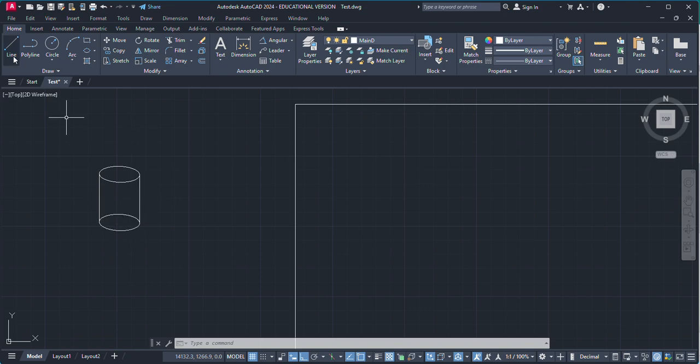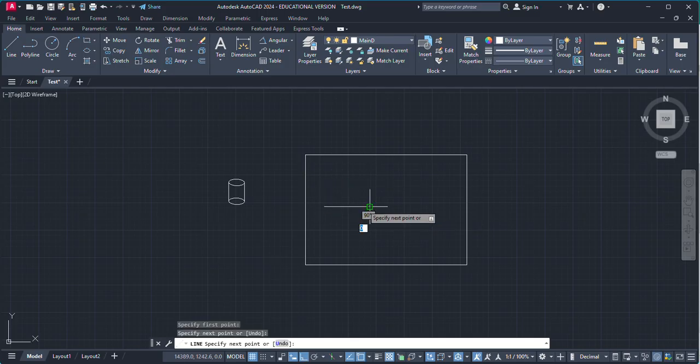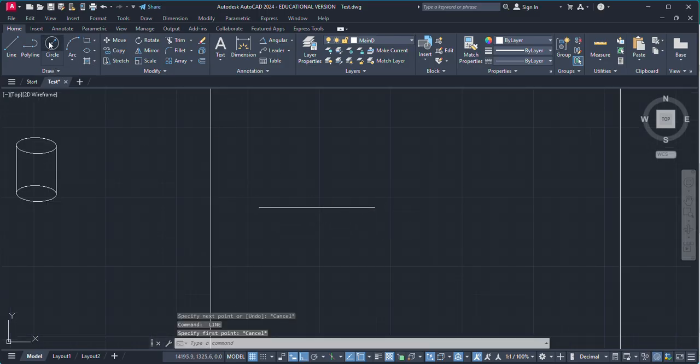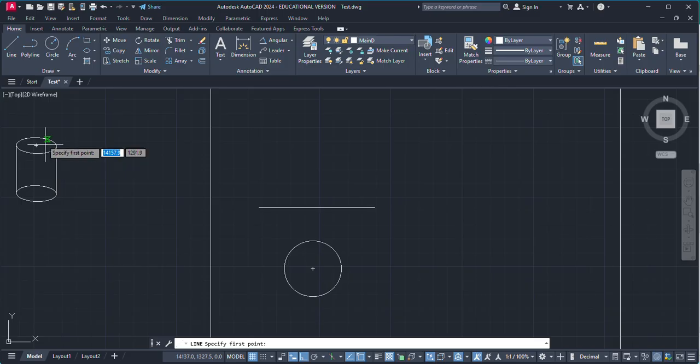view. So here this is the reference line, and suppose this is 40 mm diameter, so we will draw a top view of 40 mm. Sorry, instead of 40, we will take 20 radius. So this diameter is 40 mm. Now this is our top view, because in the top view we will have the circle, and both top and bottom circles are of the same dimension. So this is our top view, and out of this top view we will draw our front view.